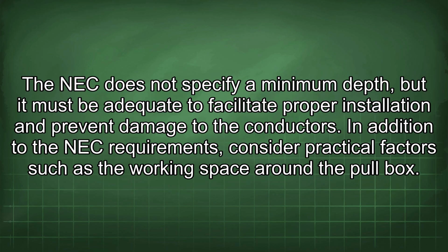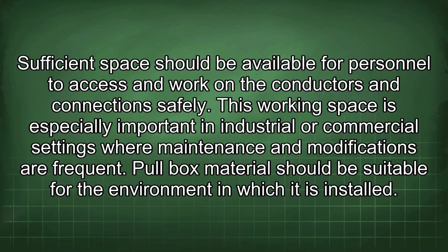The NEC does not specify a minimum depth, but it must be adequate to facilitate proper installation and prevent damage to the conductors. In addition to the NEC requirements, consider practical factors such as the working space around the pull box. Sufficient space should be available for personnel to access and work on the conductors and connections safely. This working space is especially important in industrial or commercial settings where maintenance and modifications are frequent.